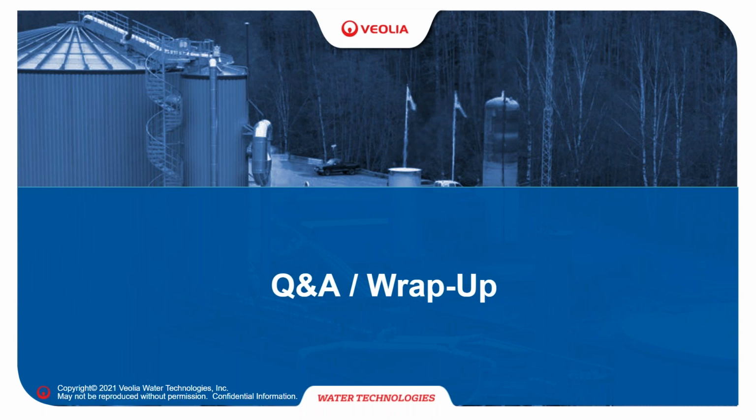All right. Thanks for those tips, Joe. It's tough to get these measurements. Usually we use Draeger tubes or Gas Tech tubes or REA tubes to measure that CO2 and H2S quality, by the way.